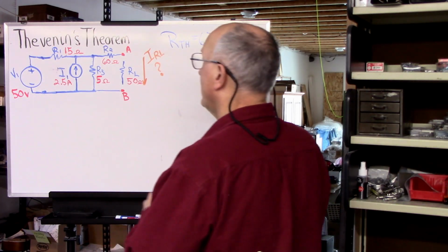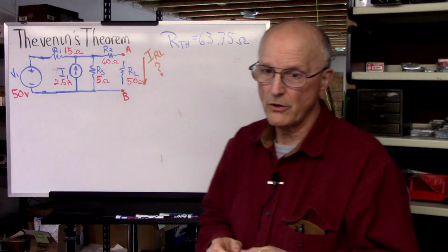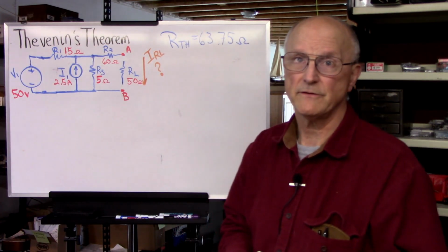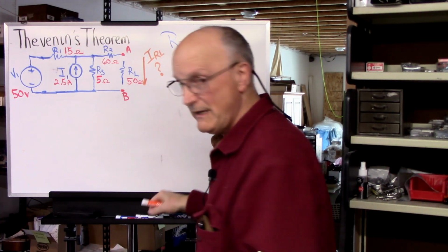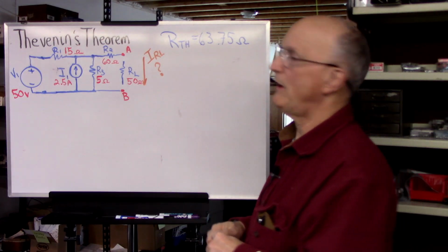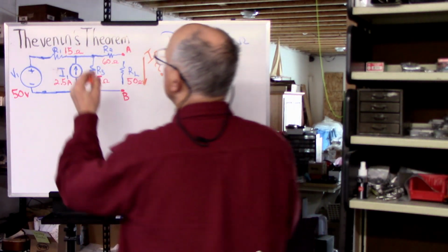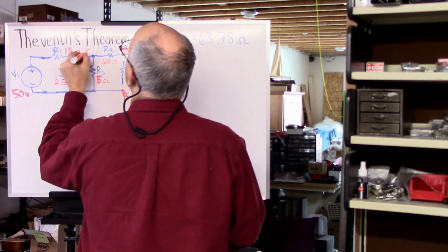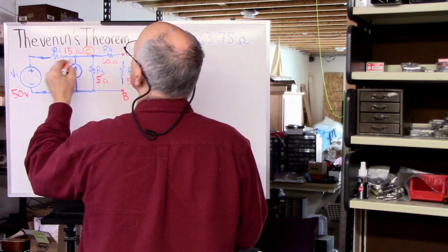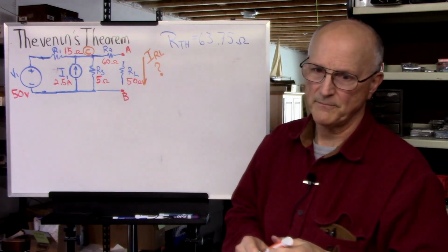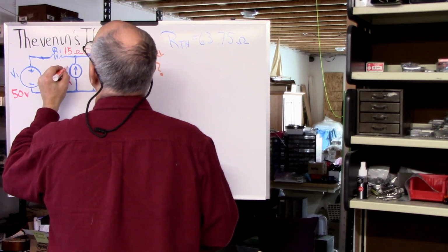So, we are going to apply Kirchhoff's current law, or nodal analysis, to this circuit. And so we're going to label the point just after R1 and before R2 as the point C. This is node C. So this whole section is node C. The current coming from the current source here is I1.